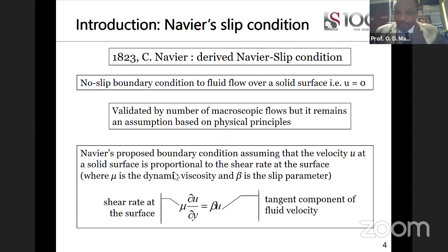You can have a surface that is slippery, a lubricated surface that needs to be cooled. In that case, we apply what we call the Navier slip condition. This Navier slip condition will enable us to take care of the slipperiness of the surface.